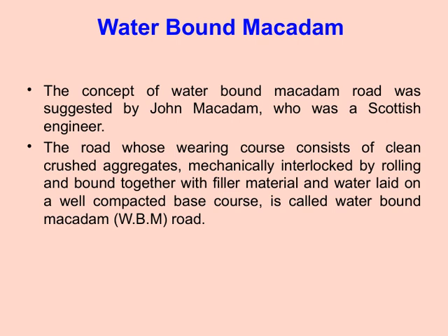Then, you bind these aggregates together with filler material and water, which helps to lock everything in place. The entire layer is laid on a well-compacted base course to ensure stability and strength. This method results in a robust, permeable road surface that has been used effectively for many years. Overall, water-bound macadam is a great example of how understanding materials and construction methods can lead to durable and cost-effective roads.